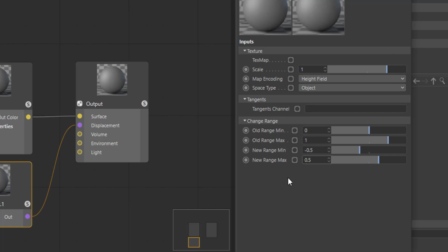Now, the scale you're going to need in here depends on the scale of the object inside ZBrush relative to the scale inside your target application. If everything's fine, and ZBrush has detected that the model was coming at a different scale but has automatically adjusted it inside ZBrush, then you're going to find that ZBrush generates it correctly with a scale of 1. So we will see how things look.